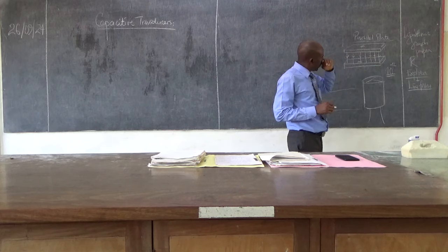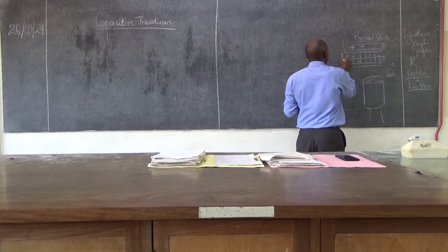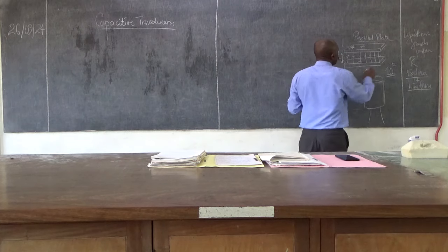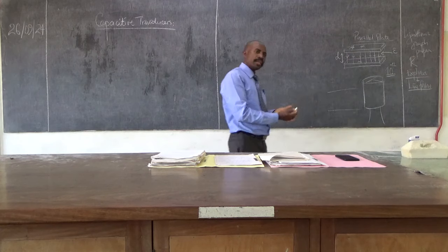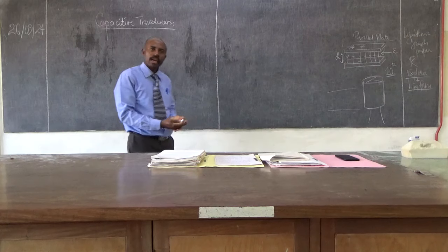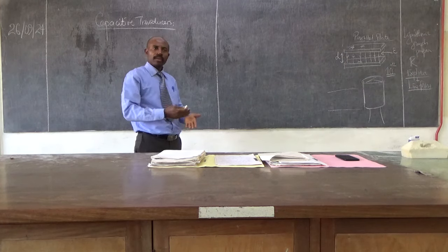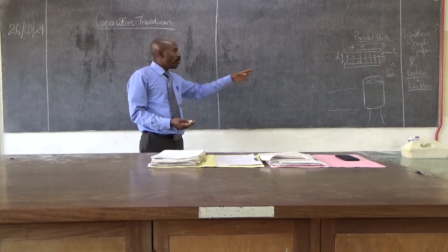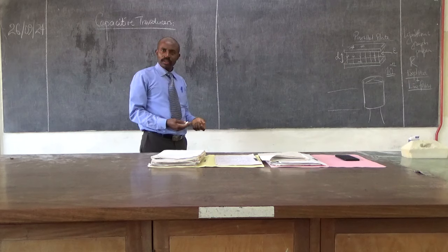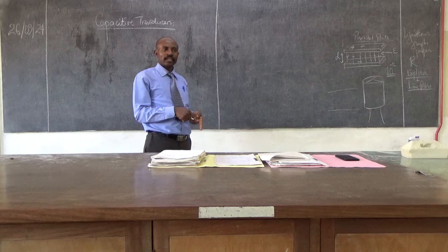So the idea would be, if this is the area, this is the separation, and then you have the material: if it is air, you have epsilon naught; if it is a dielectric, you have epsilon, the permittivity of the dielectric. So with any of those, if you change it, you change the capacitance.